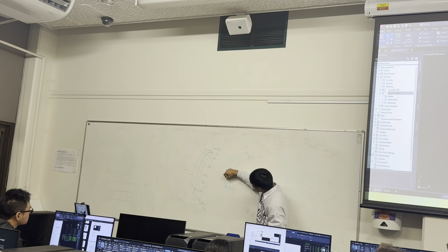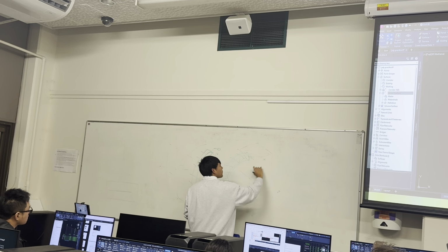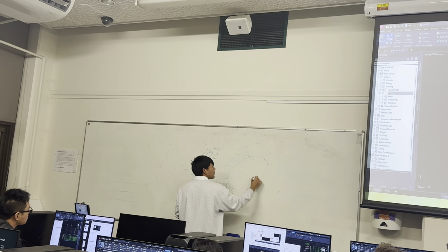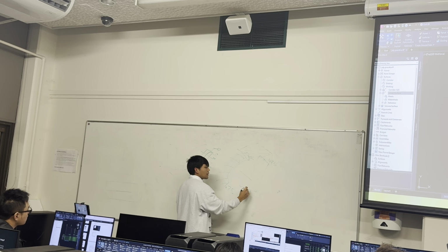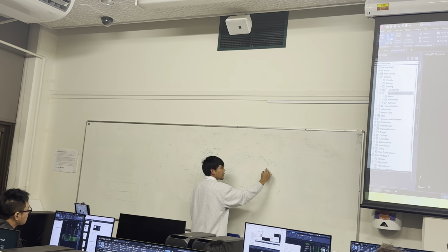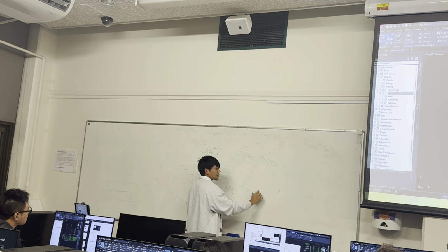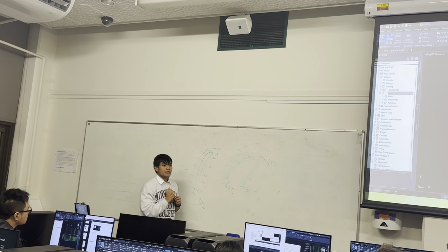And whatever is on the right is what we have to include in our cross sections. Now, if we're driving from the bottom to the top, so if we start from 0 here, start 475 here, we drive on the left side, and we will be adding whatever is on the right side of our cross sections. Is that clear to you guys?